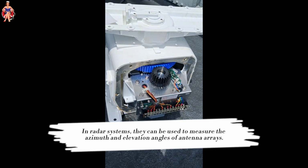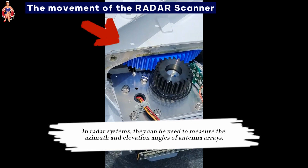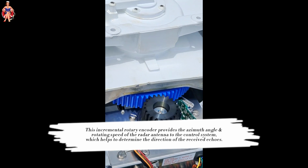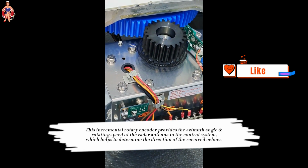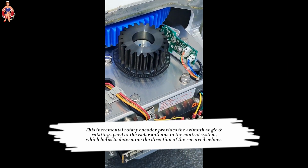In radar systems, they can be used to measure the azimuth and elevation angles of antenna arrays. This incremental rotary encoder provides the azimuth angle and rotating speed of the radar antenna to the control system, which helps to determine the direction of the received echoes.